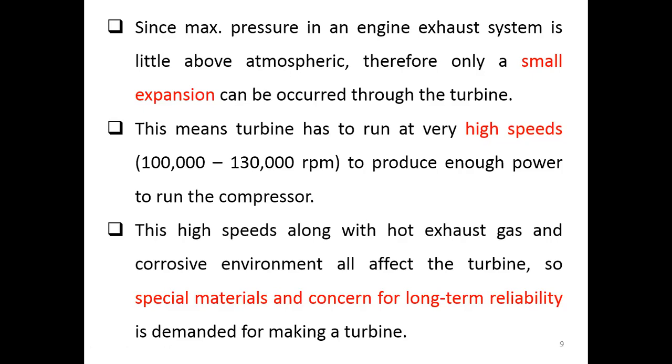Because if the expansion stroke in the engine is too high, so that the exhaust pressure is lower than atmospheric pressure, it cannot flow out. So usually we will expand until the pressure in the exhaust is just a little bit above atmospheric pressure.